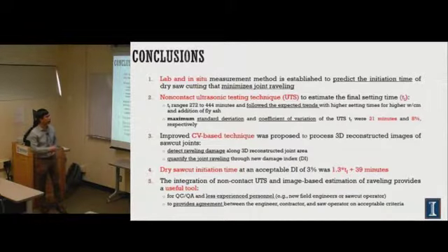The results look like they follow the expected trend, with higher setting time for the higher water-cement ratio, and with additional fly ash, of course. And the technique has a maximum standard deviation and coefficient of variation of 21 minutes and 8%, showing the accuracy of the technique too. So the computer vision can detect the raveling damage and it's quantified.